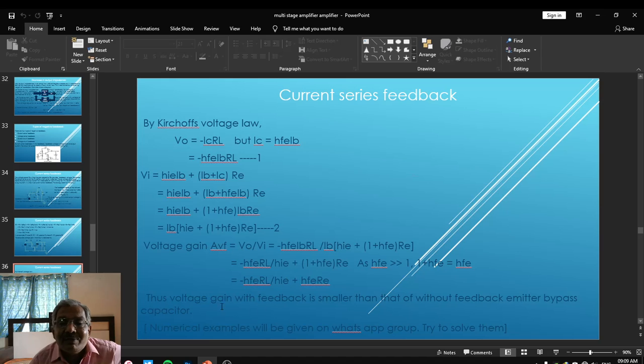When the emitter bypass capacitor is removed, then the voltage gain AVF can be written as minus HFE RL upon HIE plus HFE RE. Friends, this is how we can perform the analysis of the current series feedback as one of the types of negative feedback amplifier.